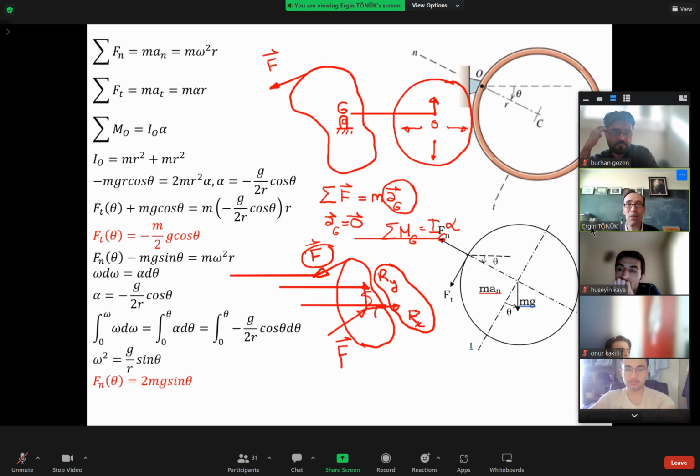So if the balancing equipment is quite accurate, the distance between the mass center and the wheel center is, say, a fraction of a millimeter, and you would feel the shaking moment at speeds exceeding 200 kilometers per hour.